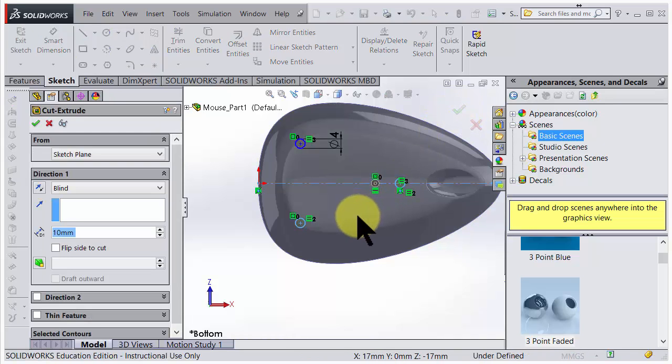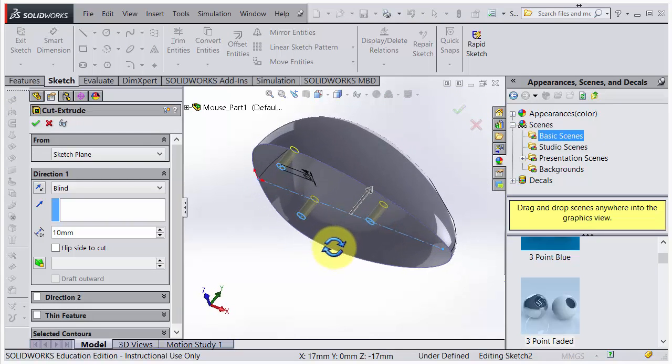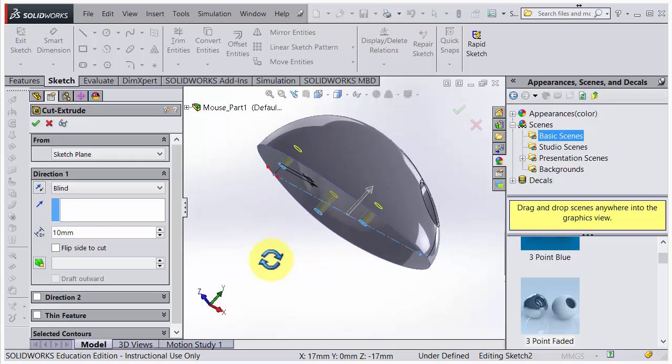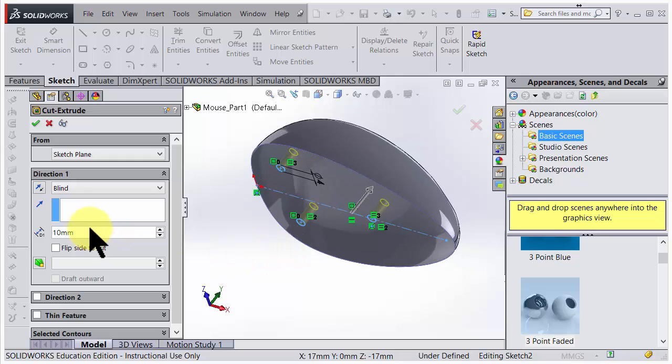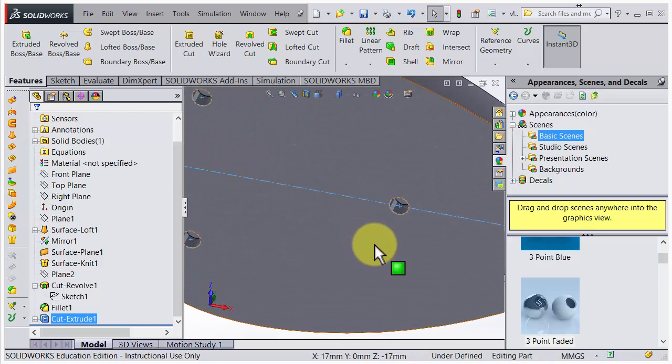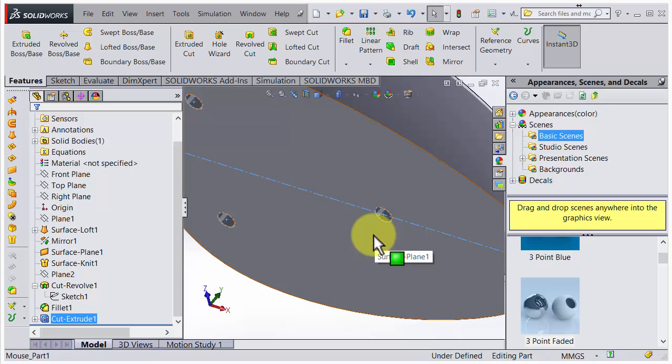We go out from the sketch, and we have a suggestion here to cut in here. So we could choose a depth here, maybe not 10mm. Let's just go for, let's say 3mm. Or maybe we could go for 4mm as well, because I would like to add a chamfer. So if I do that, we could also add a chamfer here. So we could have screws that just sink in and doesn't stick out anything from the bottom surface.